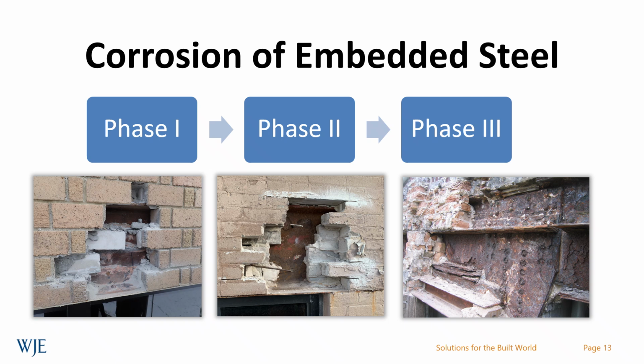In all of these systems relative to accommodating vertical and horizontal expansion in the detailing, one of the issues that frequently exacerbated these situations was the use of corrodable metal used in these instances. As the metal corrodes, scale accumulates and occupies a volume often 4 to 10 times the volume of the uncorroded steel. When this is confined by rigid masonry materials, it can also result in distress and displacement as that scale accumulates and becomes more and more severe over time, until ultimately potentially dramatically impacting the structural capacity of the individual members or the assembly in general.